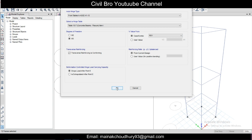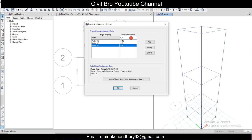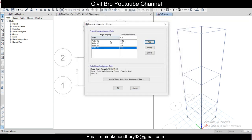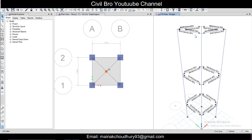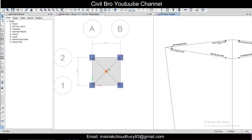And add, and 0.9, click on add. Now PQY. So for the beams, this is done, and now click on OK. So hinges have been created. You can see these two hinges, one at the near end and one at the far end. So at 0.1 and 0.9 hinges have been created.